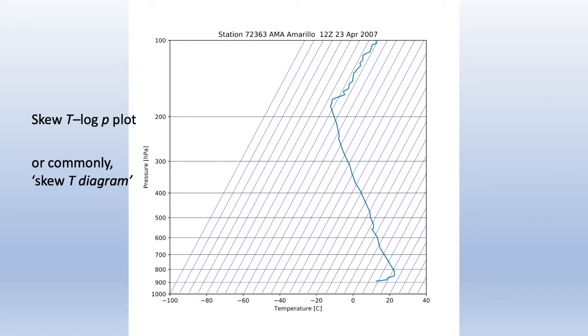This is now a convenient opportunity to give names to the curves appearing on this plot. To start with, we have isotherms, which are the lines of constant temperature. We didn't really have to name them before because we had a horizontal axis in temperature, and so you just had to look straight up from every temperature value and know what temperature you're at. Now you have to follow those isotherms to know what temperature corresponds to a particular point on the plot.